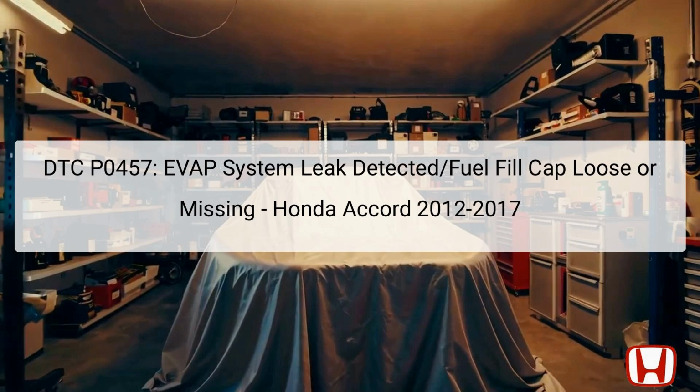This DTC can be confirmed by checking freeze frame data, where the system captures the conditions leading to the fault. It is crucial to follow troubleshooting protocols closely, as incorrect testing procedures could cause additional damage to the components involved. Proper installation of the fuel fill cap is essential, as it plays a significant role in maintaining system pressure and vacuum, which is vital for optimal performance.